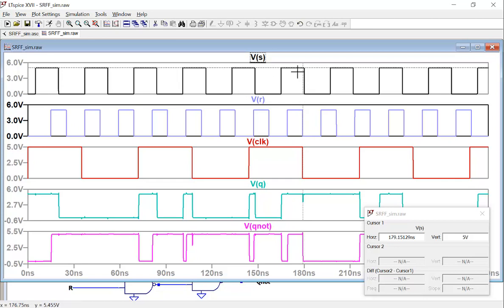If R becomes 0, S was 1, then actually it should set the circuit. So it actually worked a little bit. But after that, during a really short period of time, when it arrives over here, what happened? Got zeros. It's a memory, so it's not changing anything. So actually the R, the falling edge of the R, really affects the result.